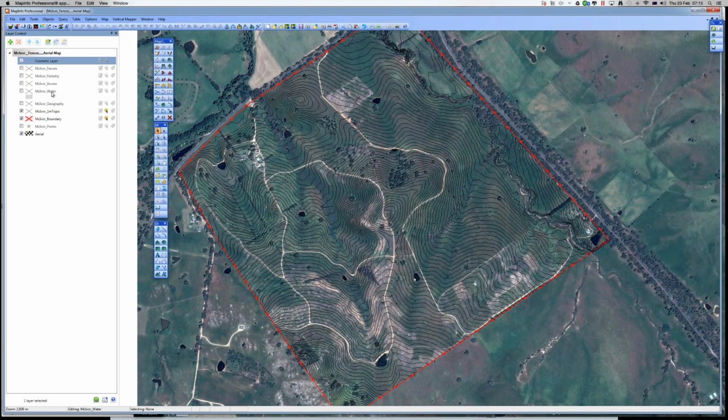You want a couple more layers within layers so that you can turn things on, turn things off. Also realize that they are physical layers. So if I, for instance, build a dam and I want to show a pipe on that dam and I put it all in the water layer, then the pipe will disappear in the polygon of the dam that I've just drawn. What I mean by that is, I'll show you.